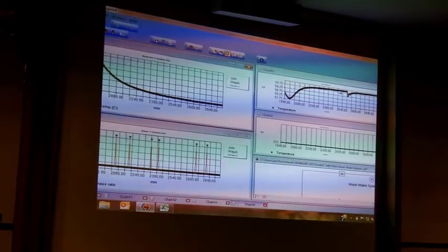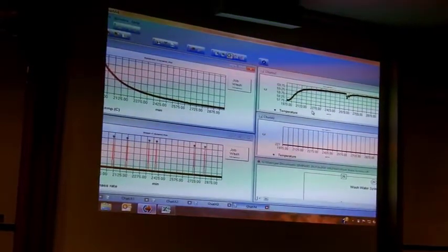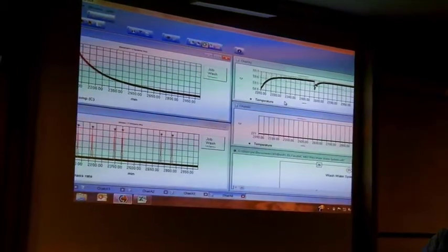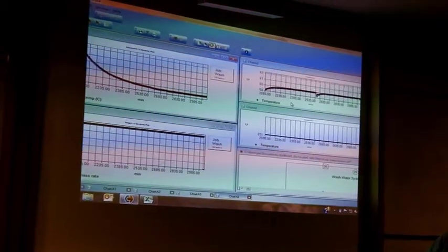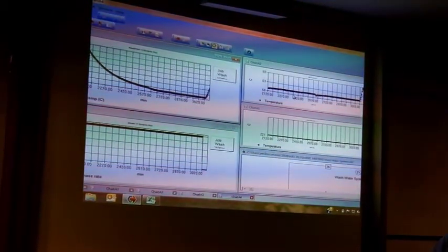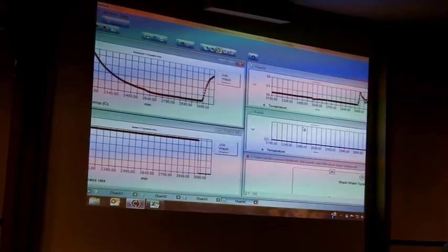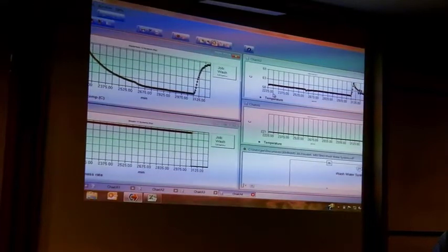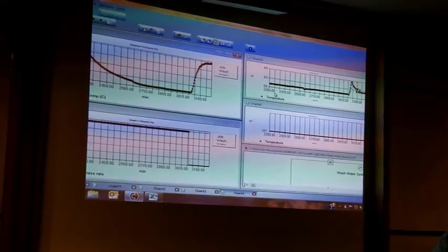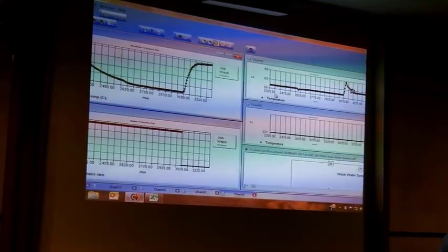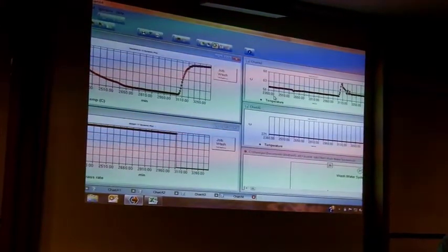There's some variation going on in there as well, but again, that's down to step times. I could get rid of those. What I can do is change the step time within a simulation, so I can say from 0 to 1000, I can have a 5-minute step time. But when the relief valve lifts, I can change it to 5 seconds.